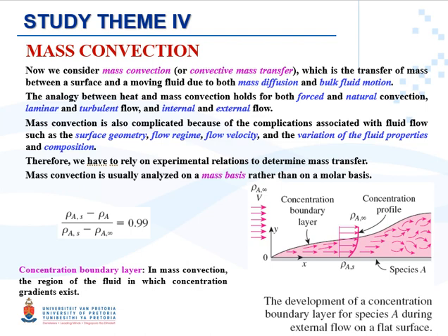Why? Because the nature of convection heat transfer was really complicated. To find the h, which was the convection heat transfer coefficient, we had lots of problems. That was the reason why we had to use semi-empirical correlations to calculate Nusselt, and after that, based on the Nusselt, calculate the convection heat transfer coefficient.